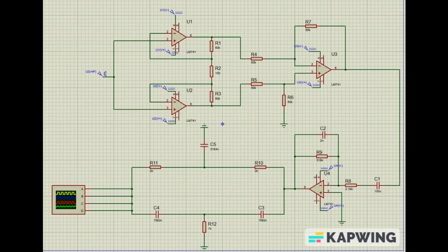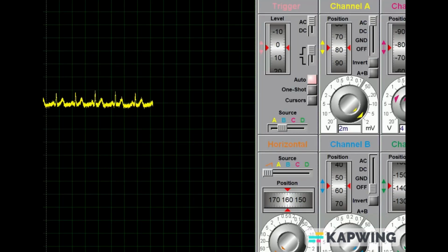Our last step involves inputting and testing all signals. The process involves taking a noise-enhanced .wav file from an audio streaming site and loading it into the Proteus simulation software. And here, in order to see the oscillation, we connected an oscilloscope to the whole circuit, and as expected, an ECG signal appeared. Despite the distorted and noise-enhanced nature of the source file, it was still possible to extract the characteristic P-wave, QRS complex, and T-wave of the ECG signal, which is a significant achievement.